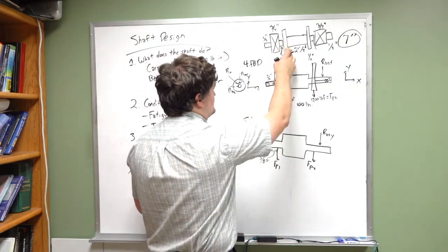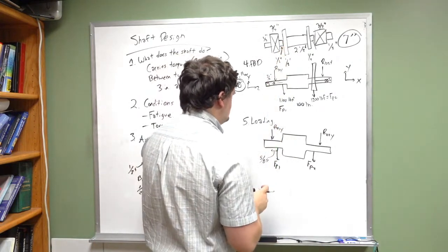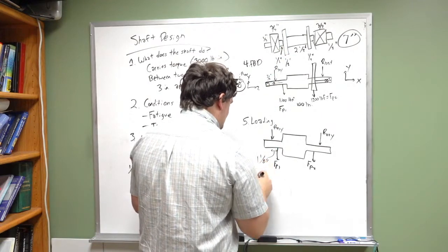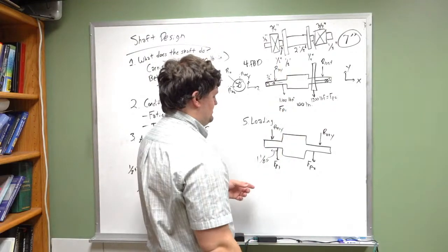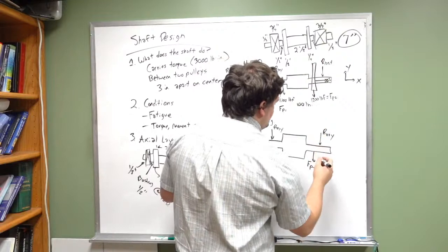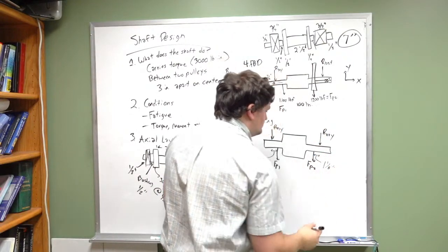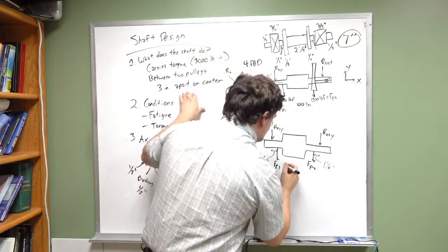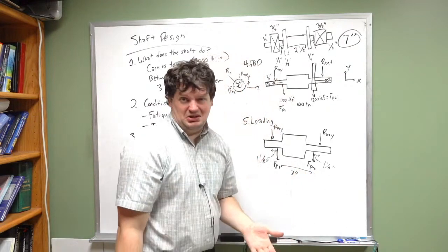So that's 5/8 inch, just by the way that we have this shaft configured, center of the bearing to center of the pulley. Ooh, shoot, I forgot to add a 1/2 inch for that bushing, which means this is now no longer that, it's 1 1/8 inch between the center of the bearing and the center of the pulley. We also know that we have the same geometry on the other side, so again, this is 1 1/8 inch. Between these two, we know that these are 3 inches apart. And that's all the dimensions we need.